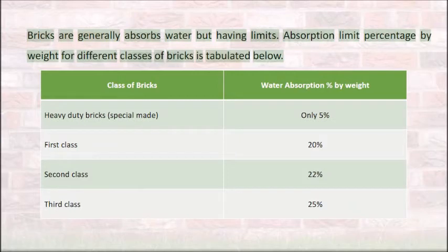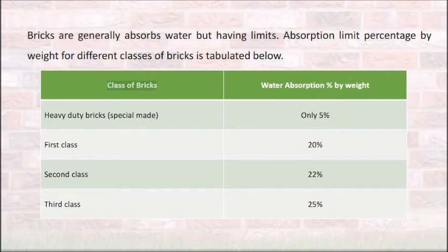Bricks generally absorb water but within limits. Absorption limit percentage by weight for different classes of bricks is tabulated below. Class of bricks, water absorption percent by weight: heavy-duty bricks, special made, only 5%.